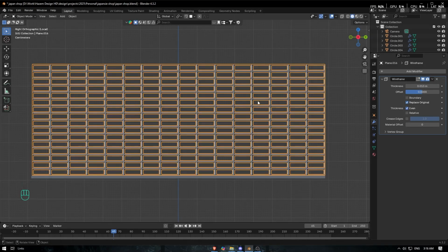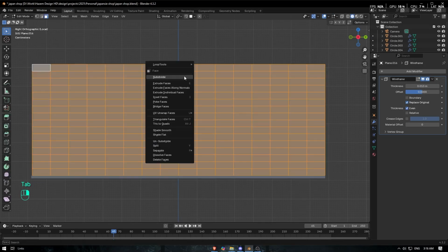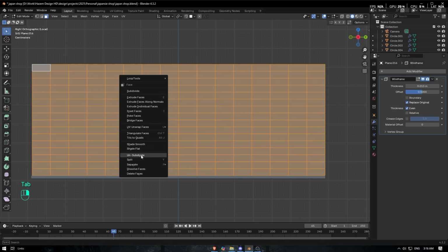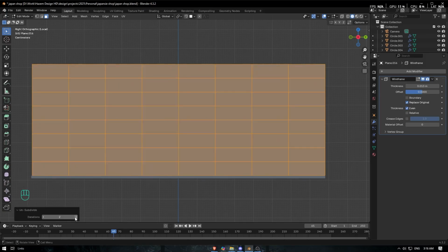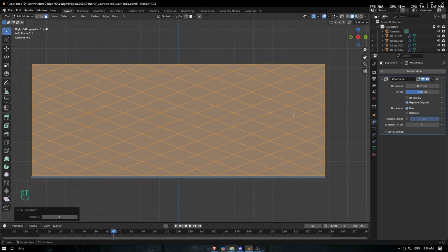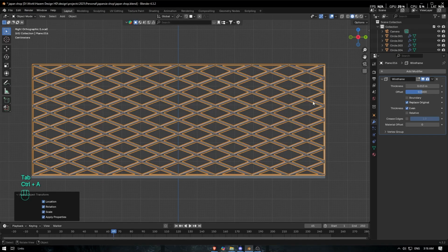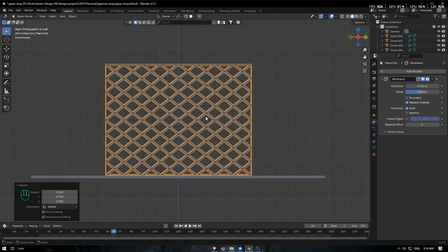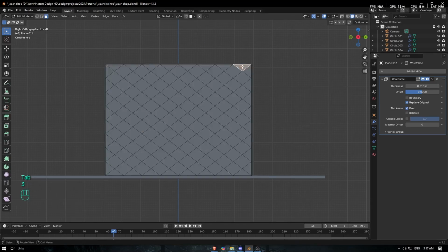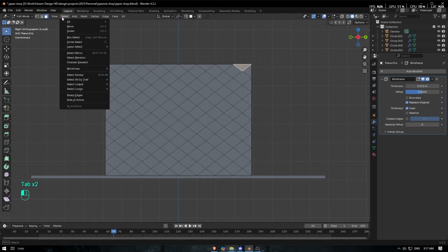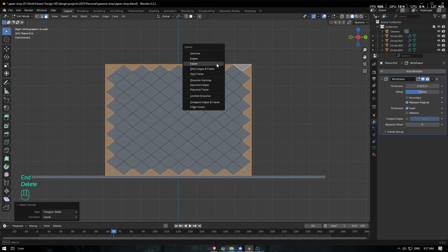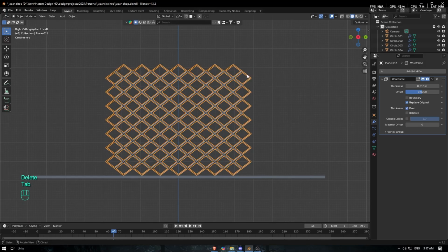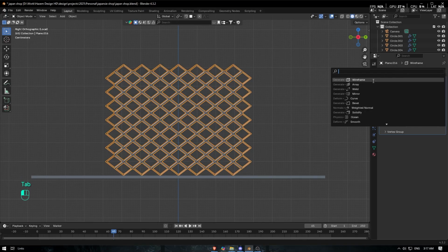This one fits well, so maybe we go here, right click, and unsubdivide, make it one, like this. Scale it down, then select any triangle or Z here from this face. Go Select Similar and Polygon Area. Then you're going to delete it and delete the faces here. And you have this one, so you can go Array